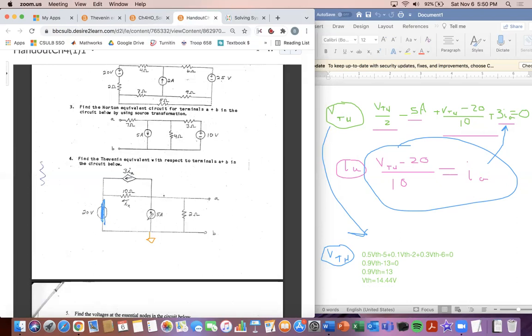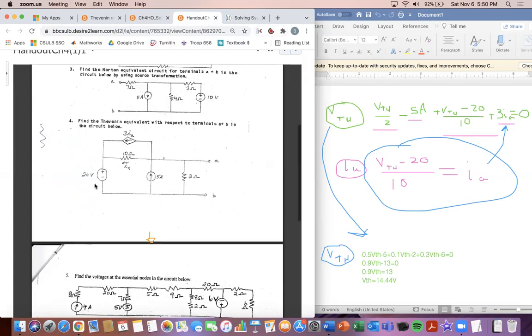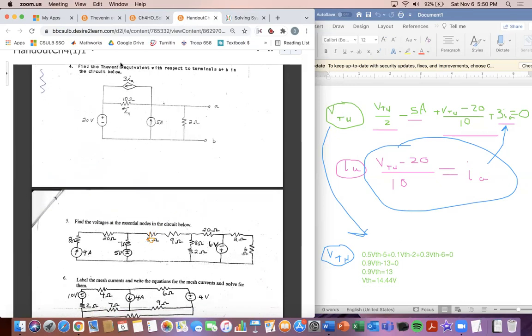And then when you deactivate a current source, it becomes an open circuit. So then this would not exist. There would be an open circuit here, and you can draw it almost without that branch even existing because it's all open. So this branch right here does not exist. I'm going to redraw that circuit to make it look better when you deactivate all those. I'll put that right here.